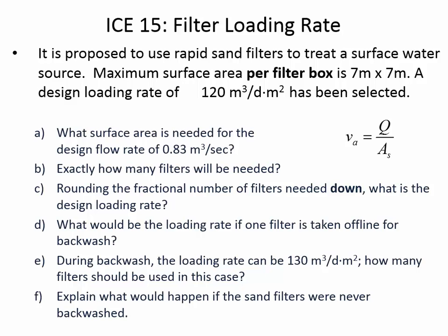What we're going to do for the in-class exercise today, does everybody have a copy of that paper, the in-class exercise? I'm going to step you through the design process and starting to think about what surface area is needed, how many filters should we break that into, and so on. Okay, so read through the problem statement, and we're going to consider we want to have no larger than 7 by 7 for each of the filter boxes.